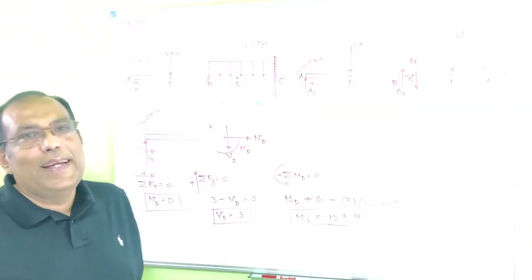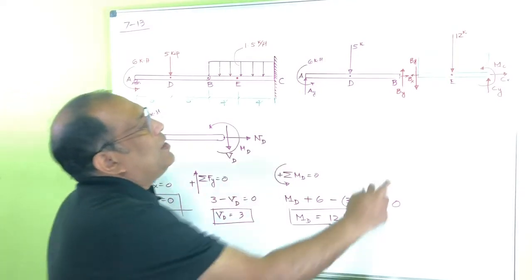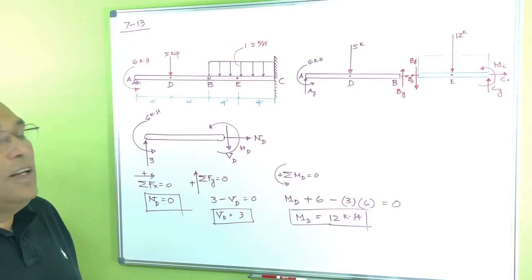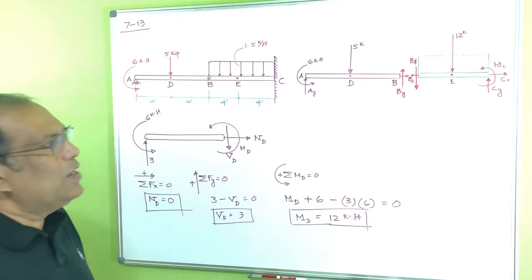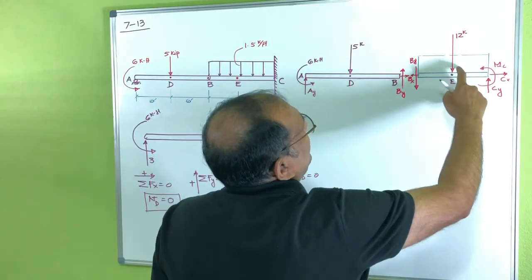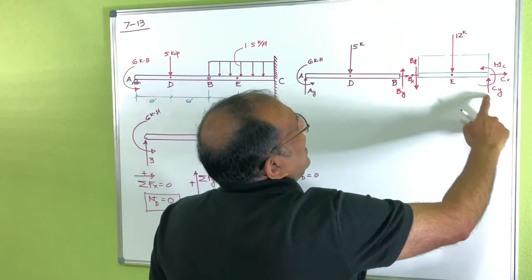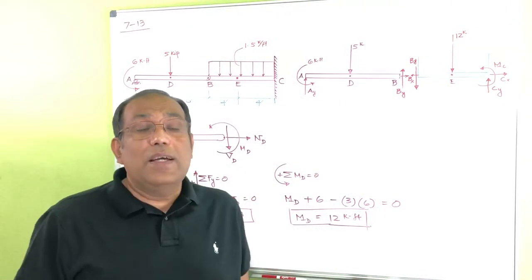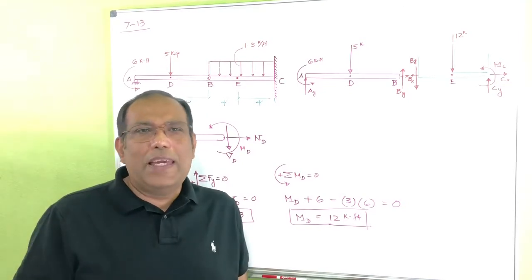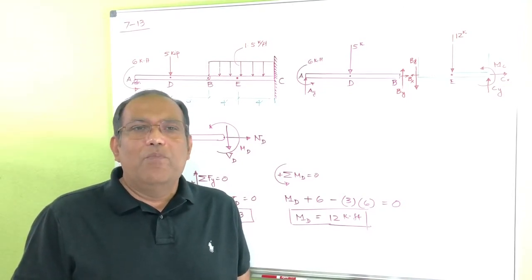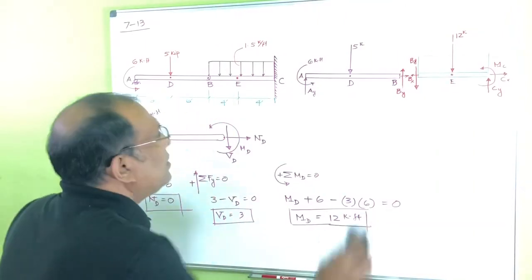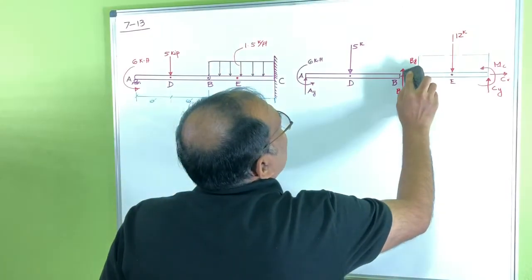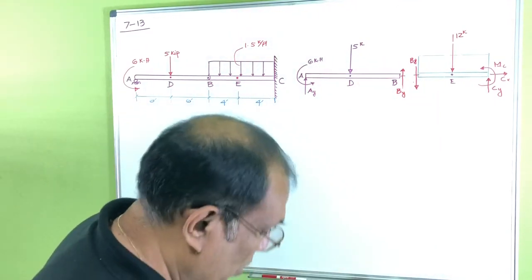Okay? Now let's try to move here and try to see, hey, what are the internal forces at point E. You can remember that when I tried to find the reaction here, I had to simplify that one. But when you are going to find the internal reaction, you have to make a cut through the distributed load too. So for example here, I know my Bx equal to 0, so I can just show this part here.